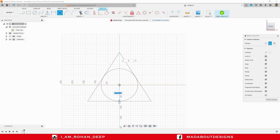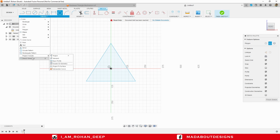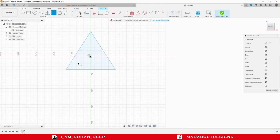Give the circle any radius. Now go to Sketch Dimension. You can directly press D to go to Sketch Dimension. Select this side and give it a length of 100 mm.